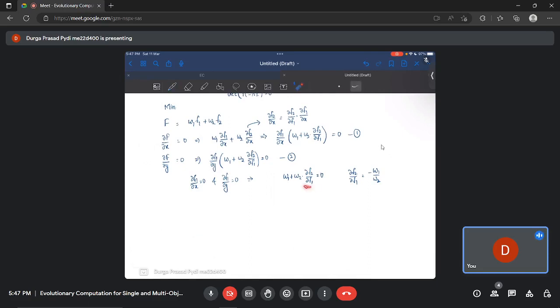It is essentially where F is getting minimized. Like this del F2 by del F1 is essentially getting calculated where these two conditions are satisfied, which essentially means your F is getting minimized, and that is equivalent to obtaining the Pareto front. So when we are solving this set of equations, what we are doing is identifying the slope, getting a tangent to the points which are lying on the Pareto front.